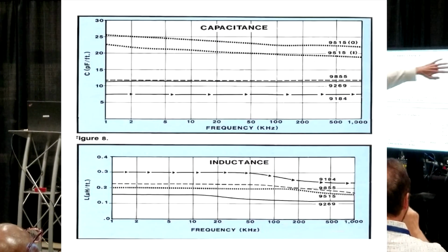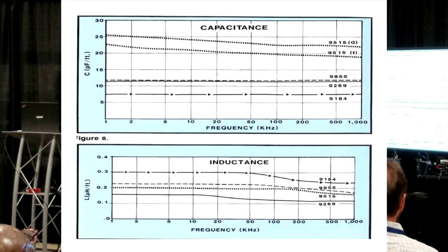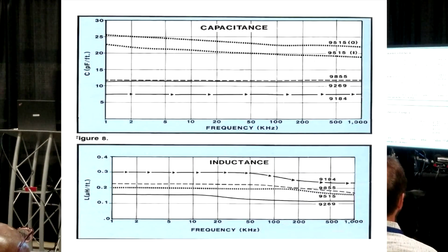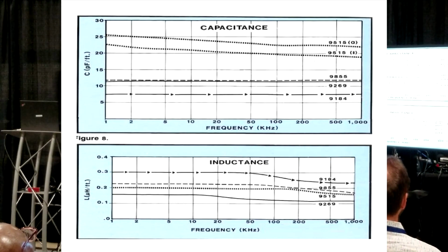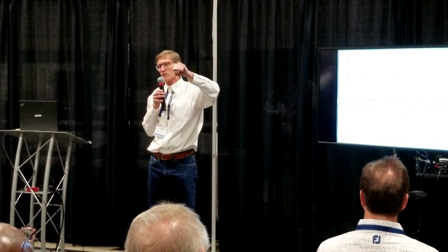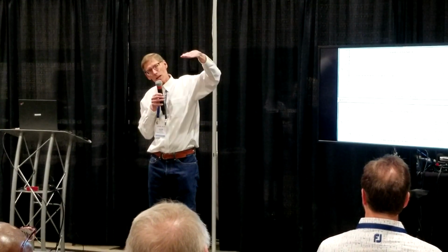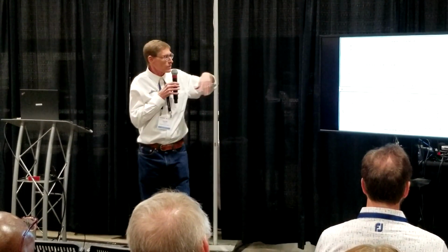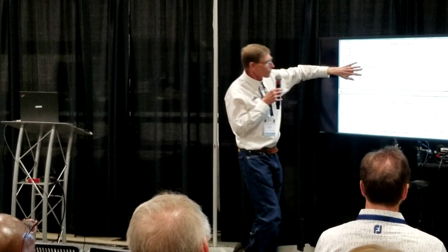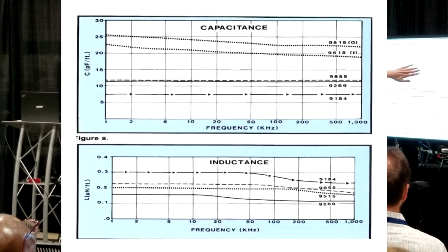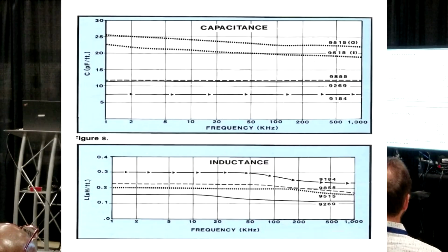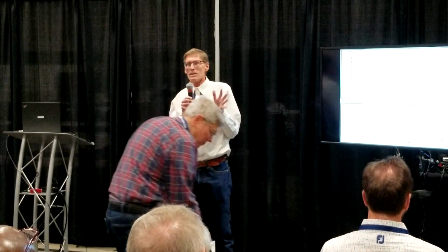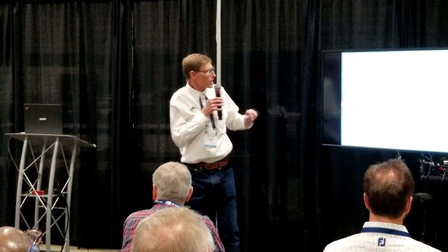These numbers are from a cable that has multiple pairs inside the same cable. So you have a cable that's got an outer pair and what are called inner pairs. And they have different capacitances. The inner pairs have higher capacitance. Why? Because they have a whole bunch of metal around them. The outer pairs are just sitting on top of the inner pairs, and then they have air above them, or basically plastic. So they'll have a different capacitance level. So ignore this. This is more like our audio cable here, where we see this nice, super flat capacitance. But that's good, because that means we don't have to worry about capacitance changing. So when we look at some of these other formulas, we can be confident that if we have a capacitance number, it's not going to change.